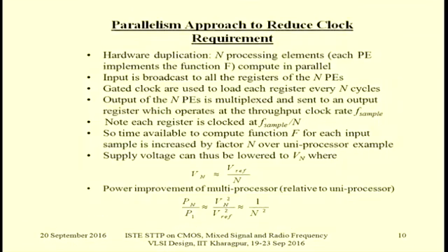The easiest approach is to take into account parallelism. That means you replicate those boxes, those logic elements, say n numbers of them. It will be better if the algorithm is such that we can do so. Consider the case of, say, matrix addition or vector matrix multiplication. That means the same operation is replicated. Then only can you have a duplication of the same logic elements. Not all algorithms are tenable or feasible so that we can apply this philosophy.